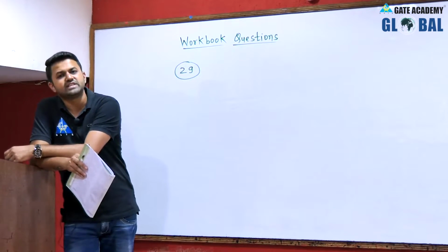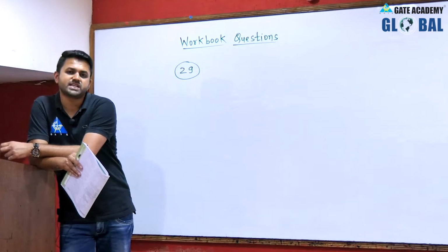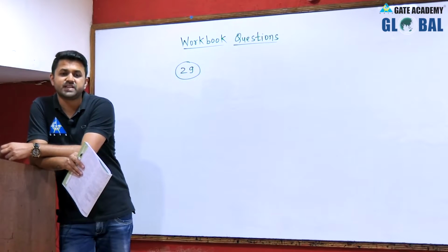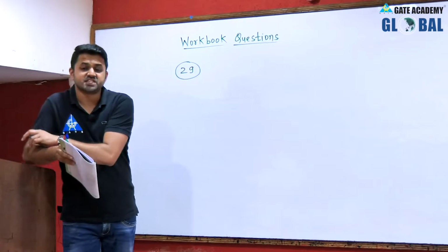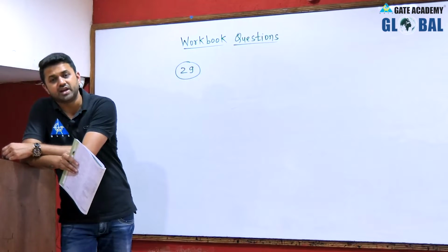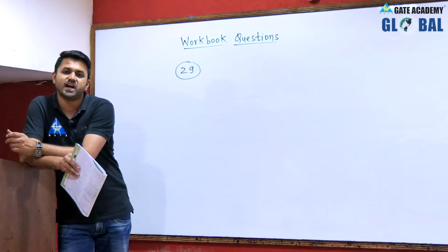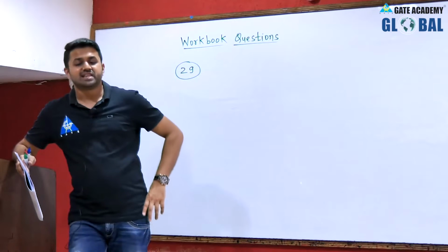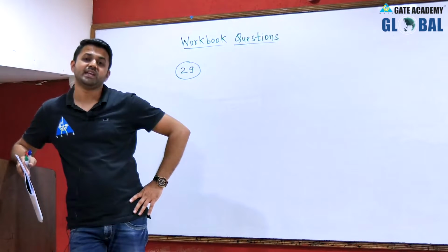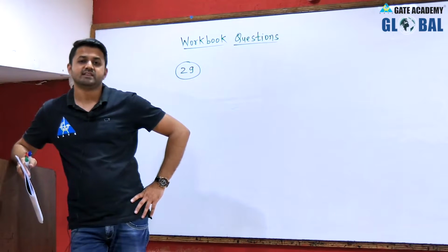If the carrier frequency is 3 f_m, then no extra component can pass through the band pass filter if the bandwidth was 2 f_m. But here f_c is very much greater than 5 f_m, and that's why even if I took the bandwidth of the band pass filter as 3 f_m, it does not allow any component other than this amplitude modulated waveform.